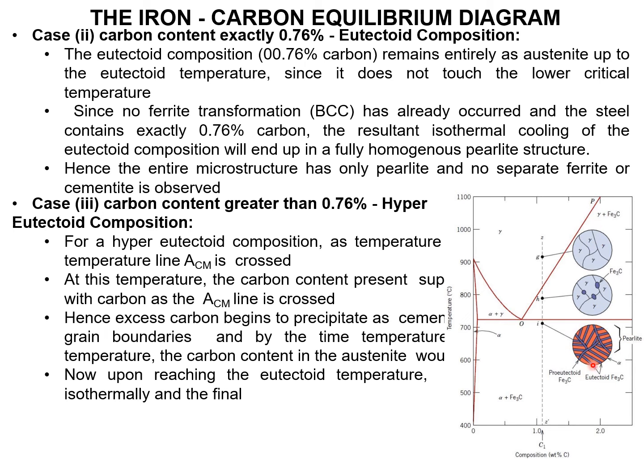See the microstructure difference. Carbon content greater than 0.76 percentage is called hypereutectoid composition. Here in hypereutectoid steel, the same alpha plus Fe3C, that is the pearlite mixture, will form, but the cementite grains are more, on the right side of the iron carbide. There the cementite grains will form. That is the only difference from hypoeutectoid steels. So this is about the iron carbon phase diagram.